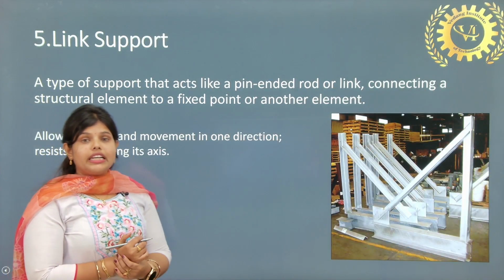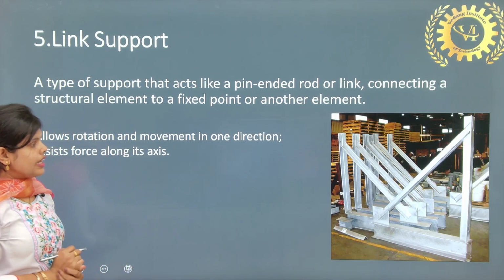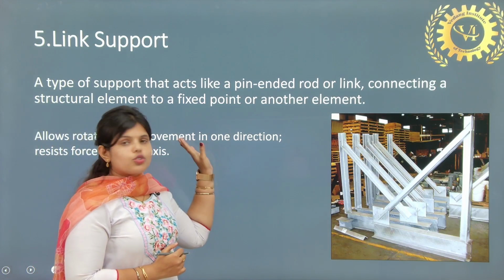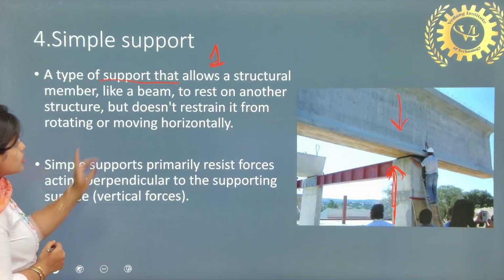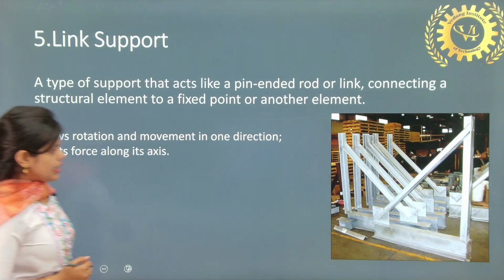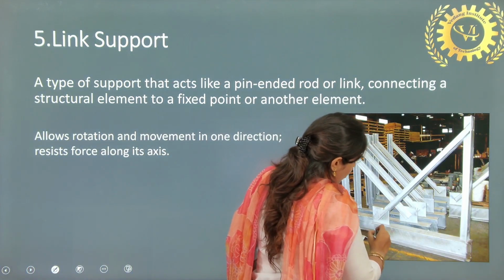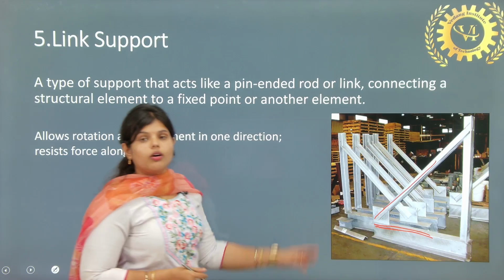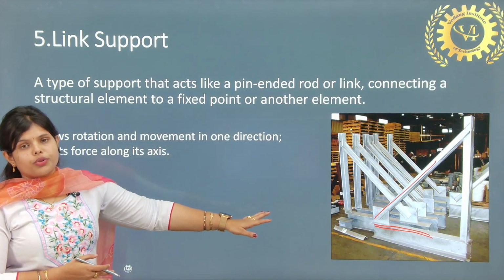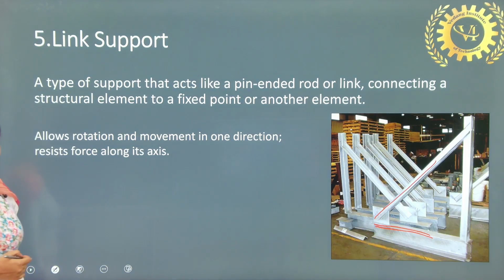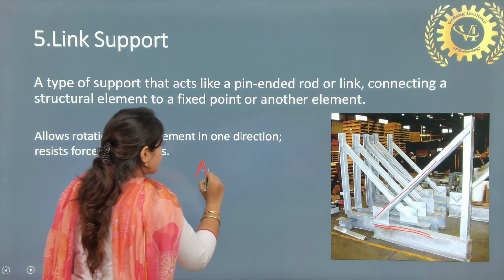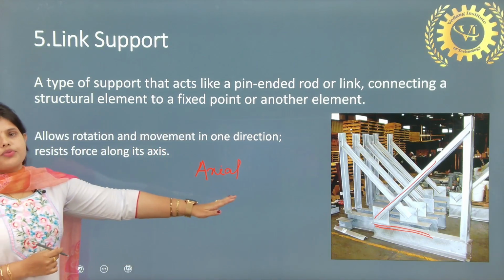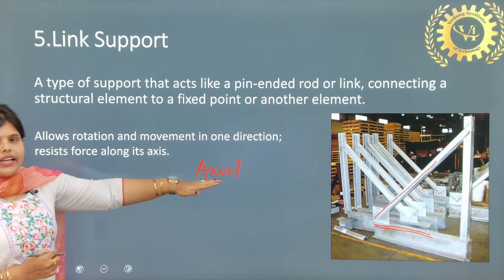Next is the link support. What does link support do? Similarly, link support is a similar kind of support to the simple support. You can see here, one support is here and another depends on the other support. In the case of link support, the reaction comes only axially, in the direction of the link, which resists the force.